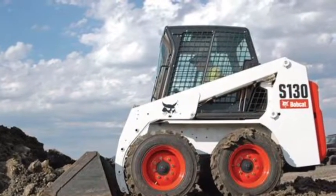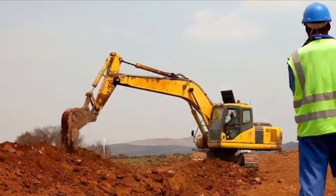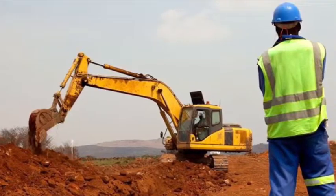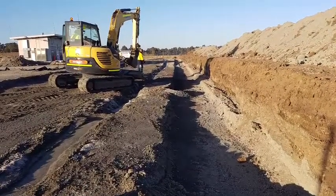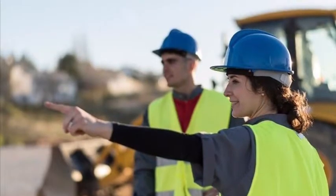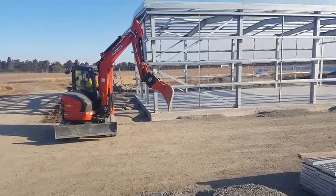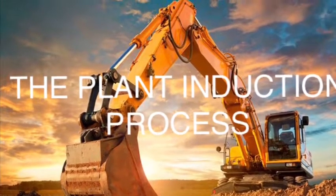When the plant arrives on site, it should be checked to ensure it's within its servicing window and has been adequately maintained. The intended operator should be trained and competent, and licensed where required, and pre-start inspections should be done prior to every use. Where required, traffic management plans may also need to be developed, implemented and communicated to all workers. All of these checks should be done as part of the plant induction process, which will now be demonstrated in this short video.